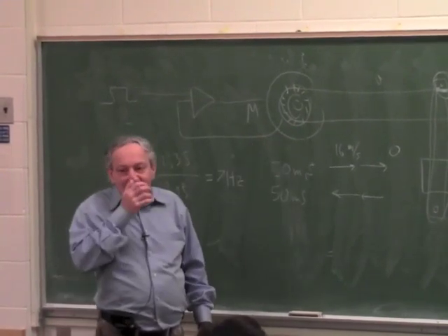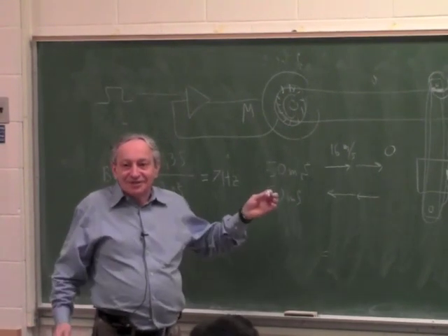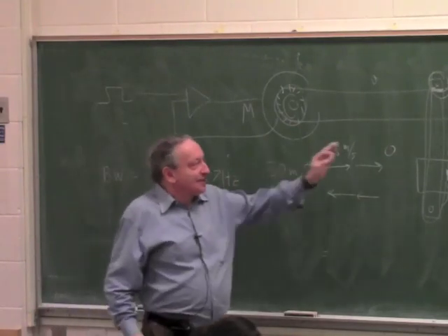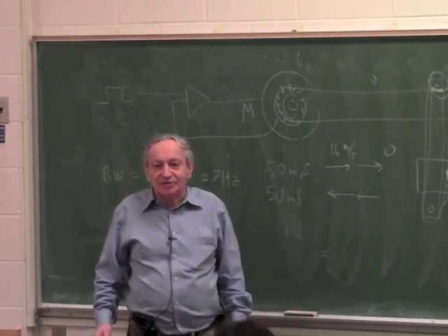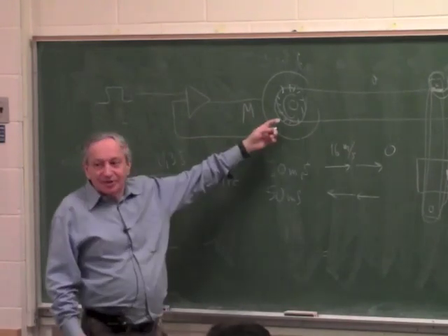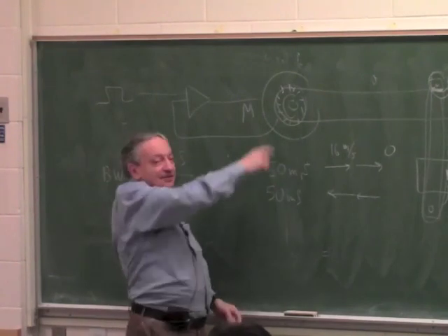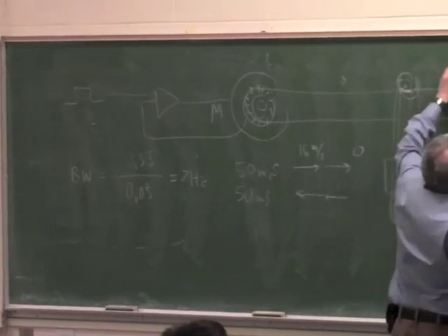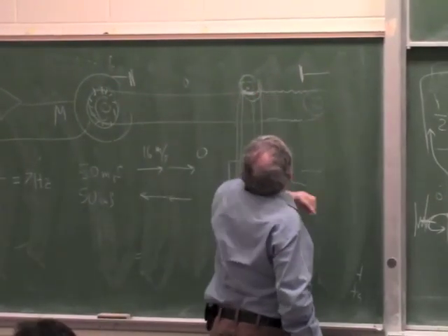One of the issues you always have to think of is, how do I know when I start where it is? Because when you start up, the motor starts running like crazy and may hit the end. So every good system design has to have some sensor. Either you put an absolute encoder, so I know where it is. In this case it's difficult because it's multi-turn. Okay? Or you just put a sensor here and a sensor here. And that's how most systems actually work.